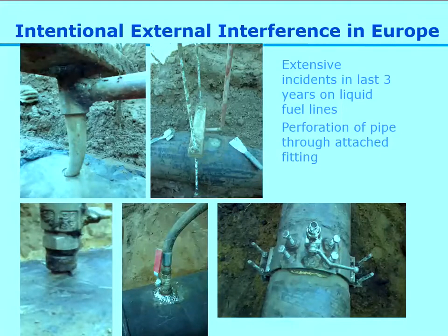The real controls that the operators have concentrated on historically in controlling external interference are for accidental external interference. The pipelines are routed through third-party land. Third parties are entitled to work on the land, so there is a possibility you have an accident. Having an accident is completely different to having an intentional damage effect. So this is a big issue at the moment. The failure statistics are high. But at the moment, other than going through criminal enforcement, there isn't a good way of preventing it.